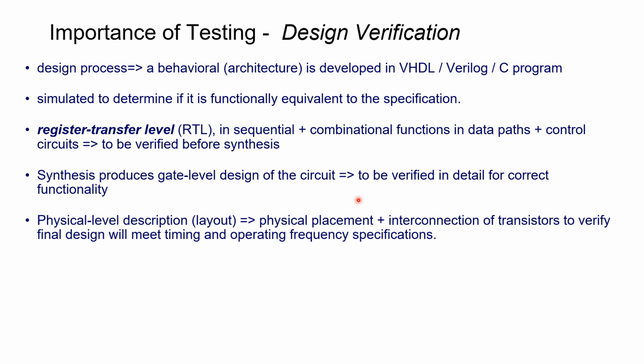So you have to face the physical components, your gates and flip-flops. Inside the library, the gates and flip-flops will be mapped to the CMOS transistors based on the technology library. Then you have to connect all the transistors to verify the final design is meeting the timing, the operating frequency, and the voltage specification. There are a lot of crosstalks. For that, you have to understand the PCB, signal integrity analysis, and reliability analysis.